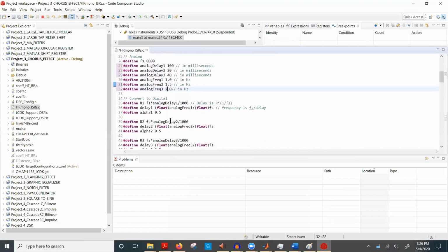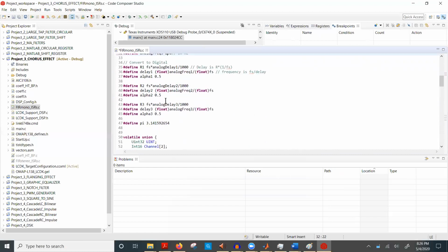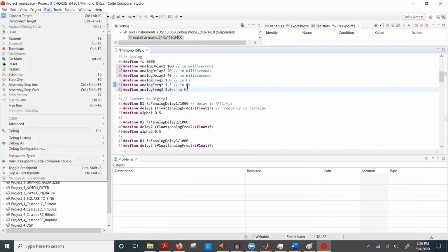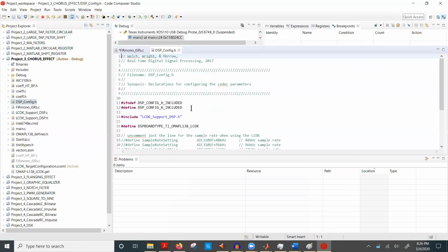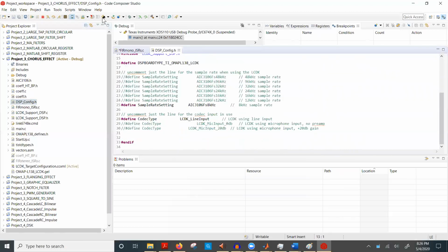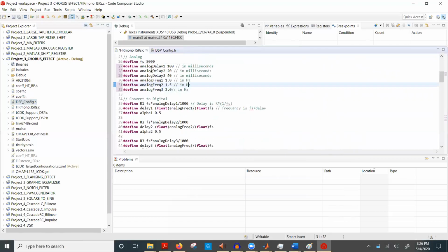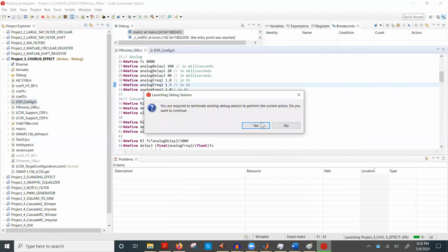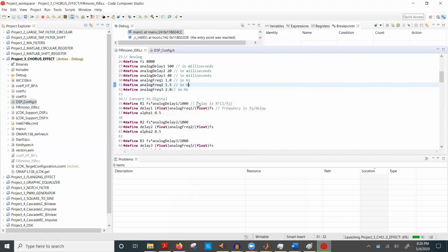I have the gains, all these at 0.5. That's probably fine. Oh, I forgot, I still set the sampling frequency to 8 kilohertz just like before, matches this up here. There's no coefficients because we're not doing FIR filters, so everything is in the code this time, in the ISR code.